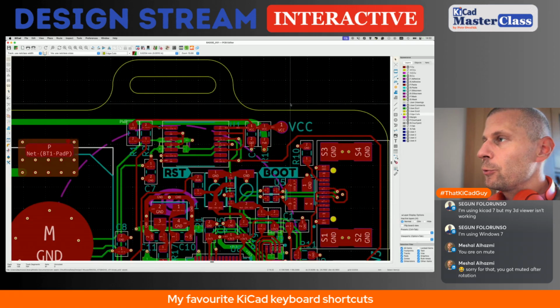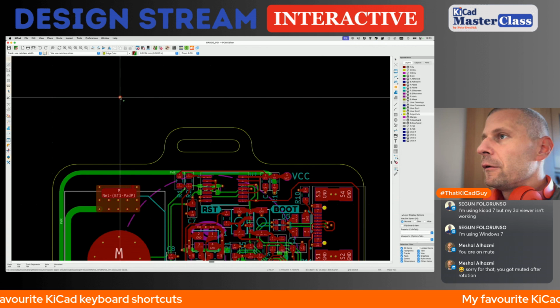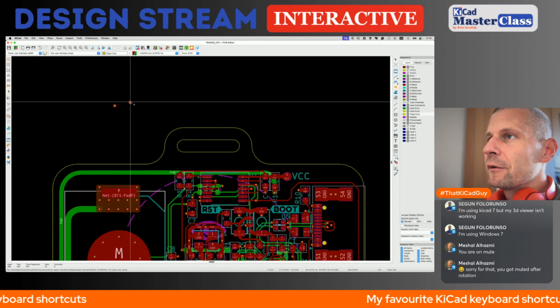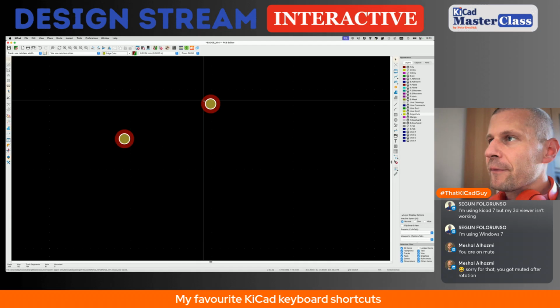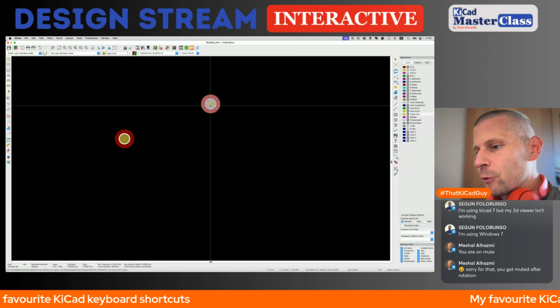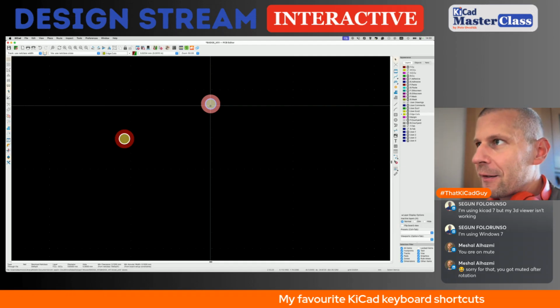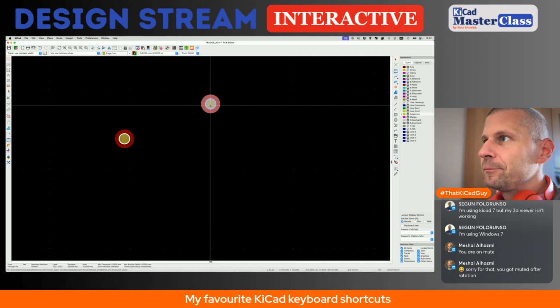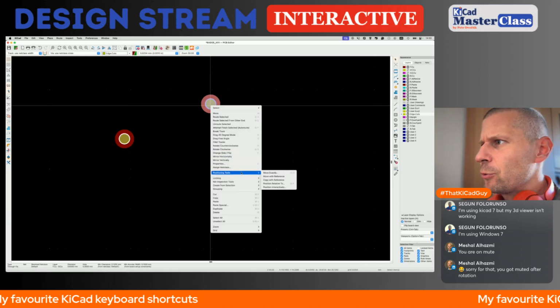Position relative to, this is one of the most frequently used features. It means you have two objects like labels, footprints, group of footprints, PCB, boards, anything. So select it and press positioning tools.